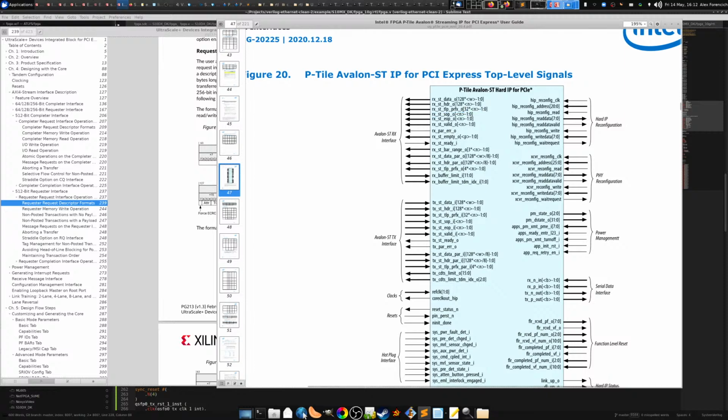And the great thing about that is that if you add or remove a TLP prefix or you change the size of the header, you're not touching the data because they're moved over a separate channel. So one, this means that the size of the TLP header now doesn't really make much difference, just in terms of, you know, where the data is aligned. You don't need to look at the size of the header to figure out how to barrel shift the data. That simplifies logic a little bit. And it also makes the header parsing logic easier because the header is always going to come out of this header interface at the same position. And you're never going to get data over there, and you're never going to get header over here. So it kind of simplifies some of the connections.